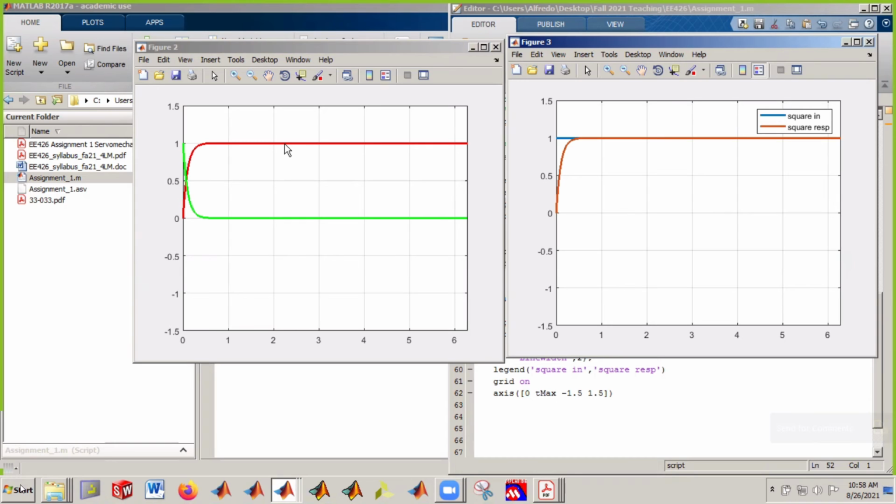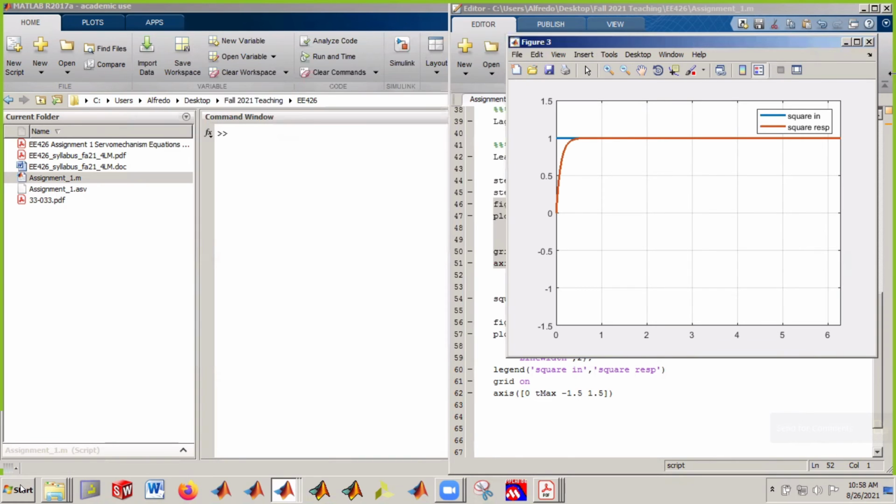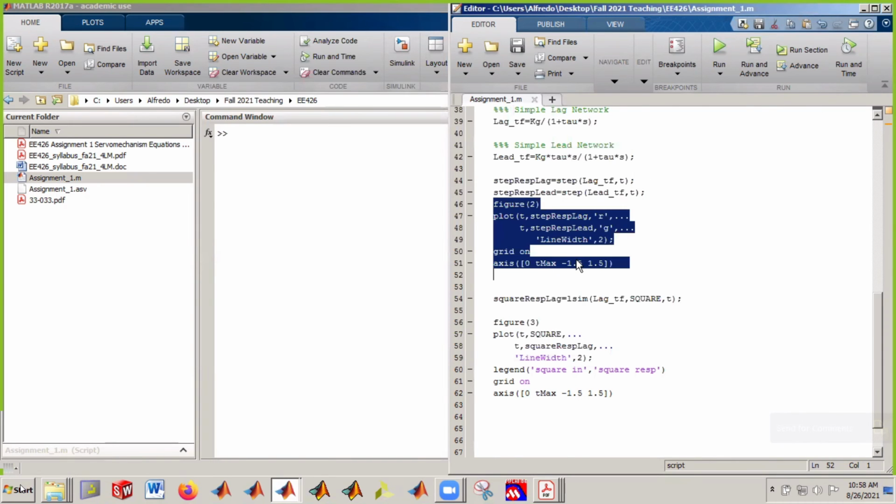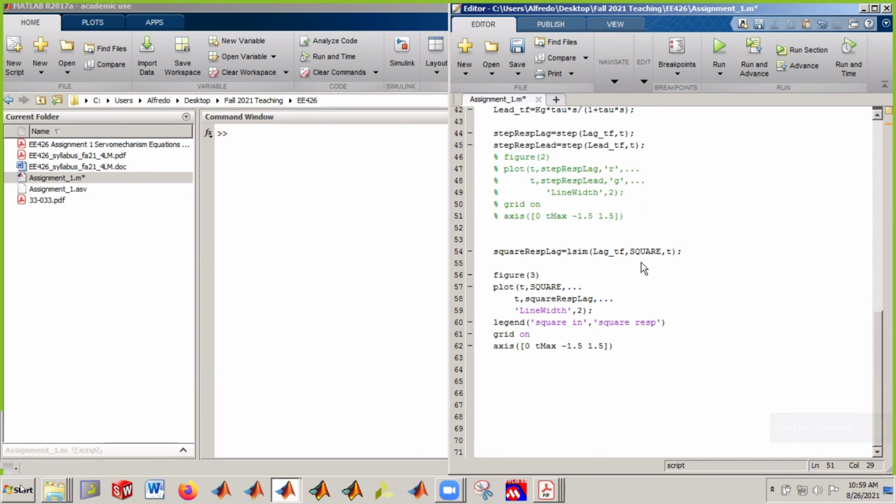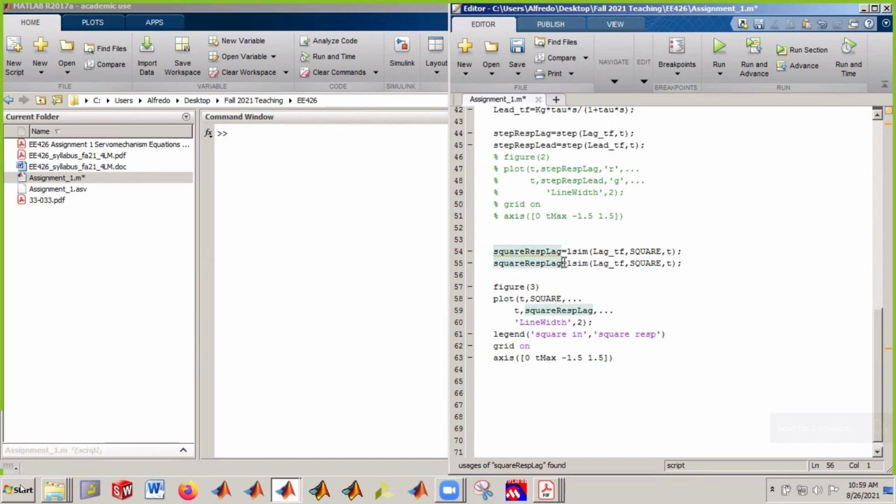Well, now notice with the LSIM, we can control it. We can even plot the same input right here, right? So the blue one is the input. The output is the orange one. In this case, we're just showing 2 outputs here. So that is why you need to get used to using the LSIM command, because this is what we really care about.